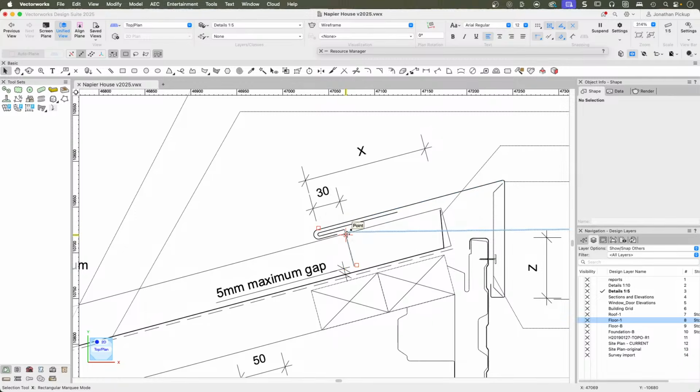Now there's a couple of tricks that this detail is using to stop the water getting in. Number 1, it's got this flashing that comes down. This flashing is designed to try to prevent the water from getting up there. But if any water does get in here, then there's a stop end. They bend the steel up, they bend the roofing material up, and that stops the water being able to get up and over the edge. It's got to go uphill against gravity. But it's got no kinetic energy by this stage because this flashing has stopped the wind. So that's kinetic energy.